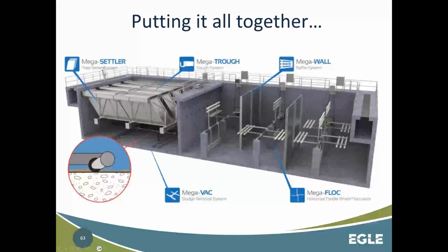And this one I like because you can see they've got 3 boards on here, 3 boards on here, 2 boards on the last one. And that's what I was referring to as far as being able to have 2 ways to reduce your mixing energy: reduce the speed and reduce the surface area of your paddles. They've also come a long way with these paddles, the boards, if you will. They've got new materials that they make them out of. For a time, they were made out of materials that would degrade and rot, and they'd have to be replaced. That's gotten better.